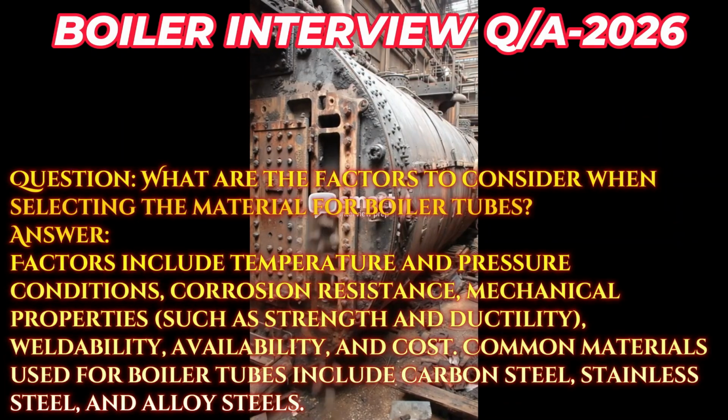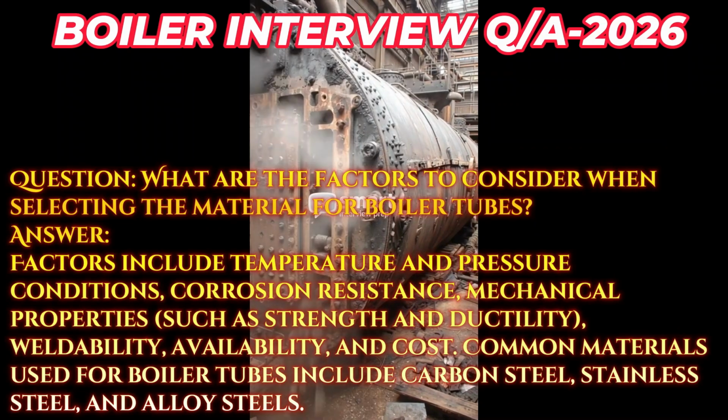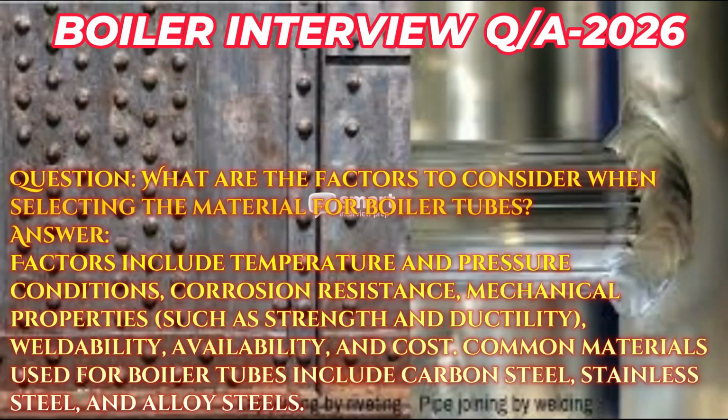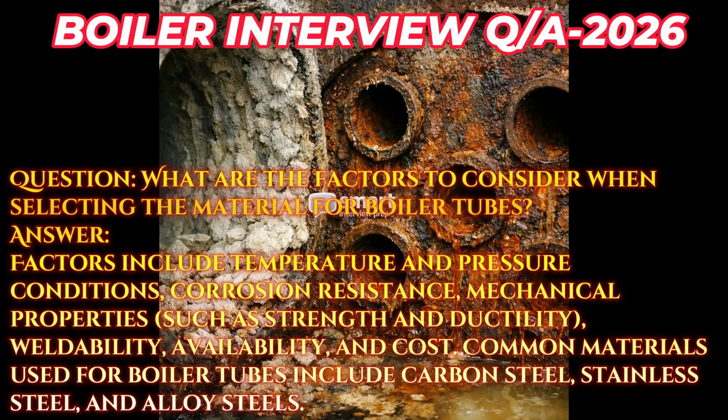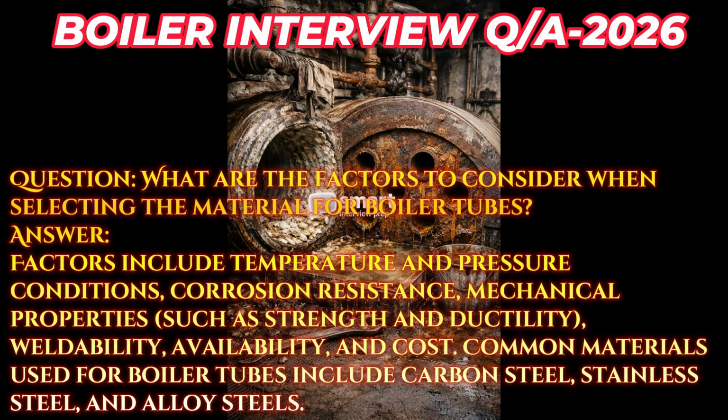Question. What are the factors to consider when selecting the material for boiler tubes? Answer. Factors include temperature and pressure conditions, corrosion resistance, mechanical properties, such as strength and ductility, weldability, availability, and cost. Common materials used for boiler tubes include carbon steel, stainless steel, and alloy steels.